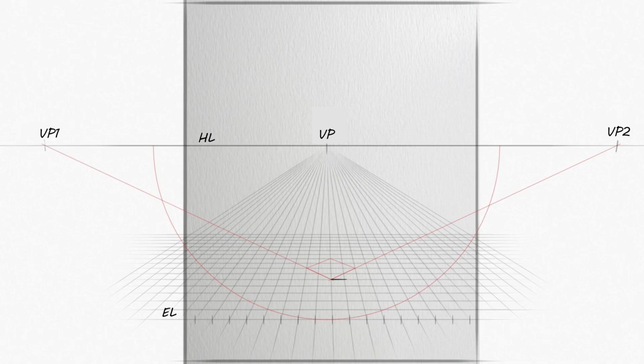We will use the exact span of 4 grid tiles to establish the true scale and length of the cube's closest vertical edge. Draw a vertical line matching this exact measurement to form the leading edge of our upcoming 3-dimensional cube. Next, project a vanishing line from the topmost endpoint of this vertical edge directly toward VP1, and then do the same towards VP2. Now, draw a diagonal line connecting the outer endpoints of both segments, as shown.